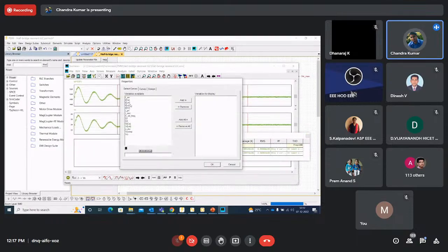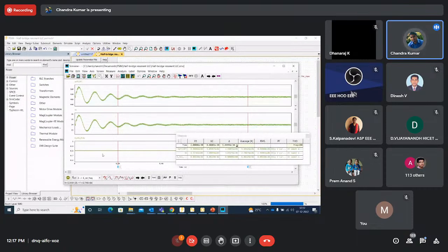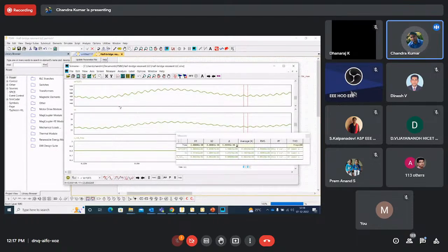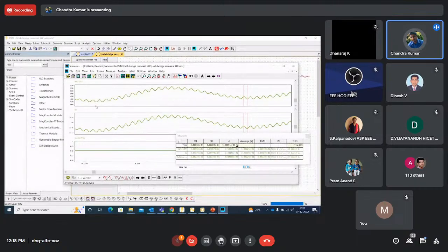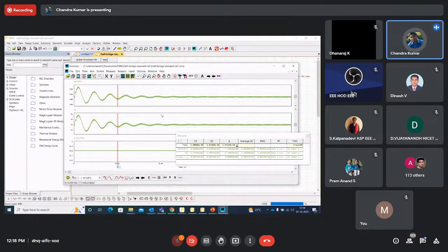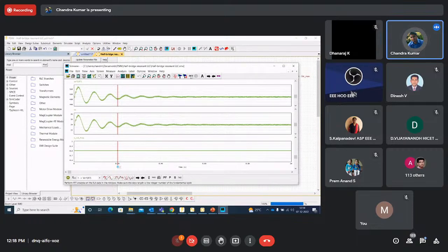You want to look at the switching frequencies. You can look at your frequencies here. See, you can calculate what is the switching frequency range. For example, if you want to zoom in, you can zoom in on the values, you can fit your Y values, and then redraw, come back to original positions, and then you can do the post-processing here. So this is a very interesting tool in terms of doing your power supply design.